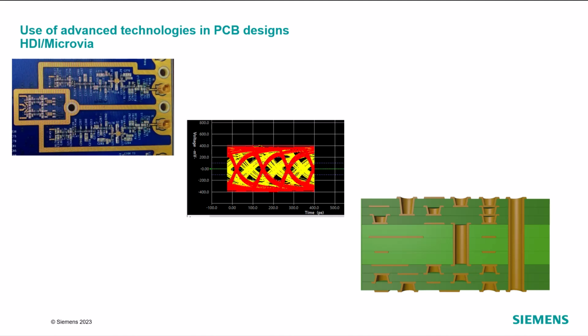Design flexibility. HDI provides greater design flexibility, allowing engineers to create complex multi-layer PCBs with intricate routing patterns. While HDI requires more advanced manufacturing processes, they can reduce overall PCB costs by enabling smaller board sizes. Because of the smaller copper features used in HDI, integrating a DFM strategy early in your design process will help you develop your design quicker and more cost effectively.